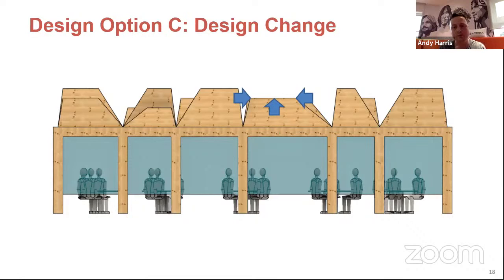And that meant it was a bit too close to the outlet. But also by raising it, we reduced the opening size, which meant that we caused the velocity at that opening to increase, which means the air is getting propelled further away from the roof of the building before it can then be caught and recirculated back. So if you click the next slide.